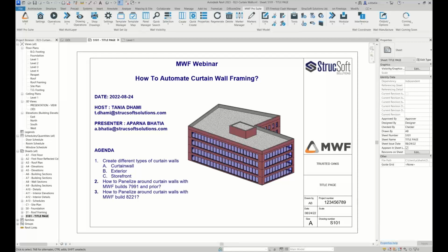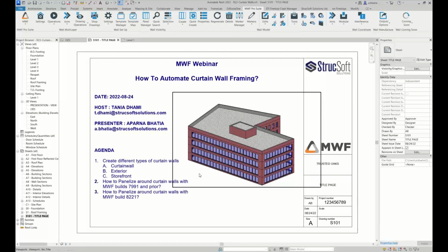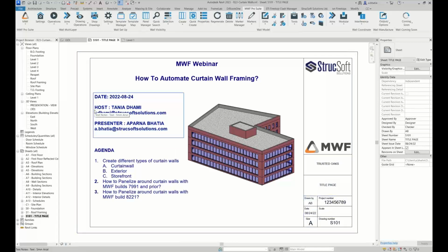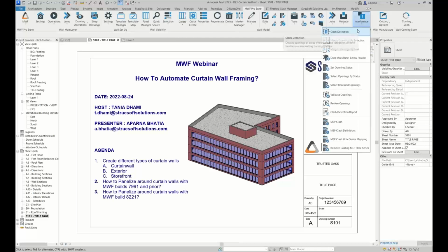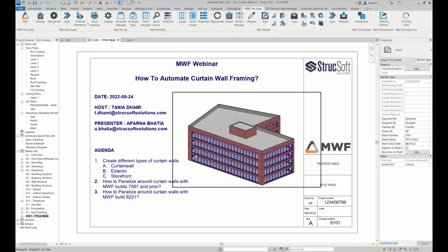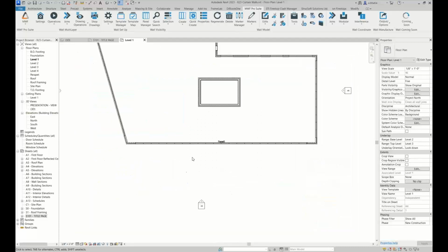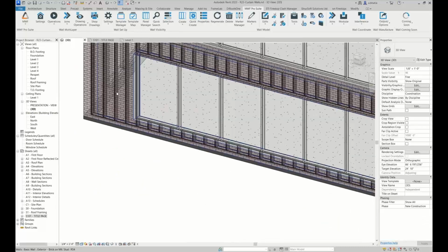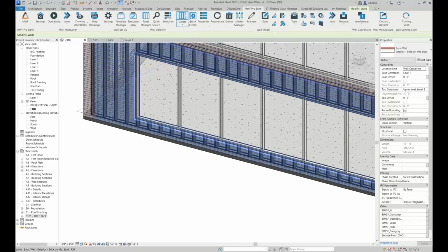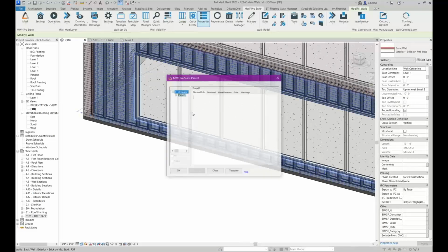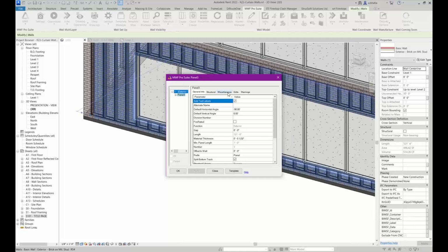One more question. Can you use set wall open mapping rules with wall openings? So do you mean within the templates, or do you mean within clash detection? Because there are two different ones. Within the template, yes, you can. Let me go to the 3D view. If I go inside the panel properties, you'll see that it's just called openings because it's a rectangular shape wall opening. So it treats it similar to a duct opening almost.